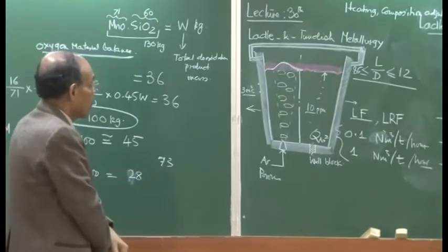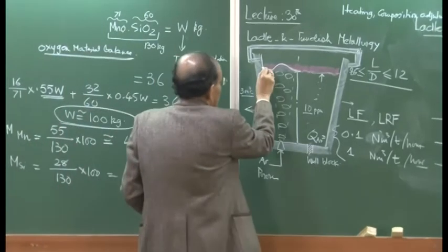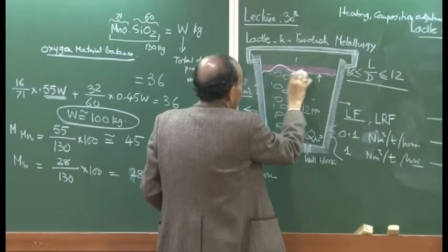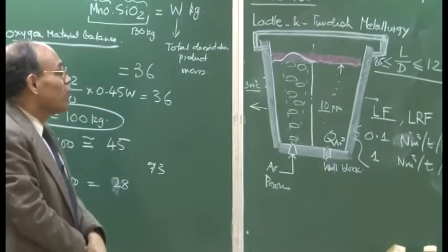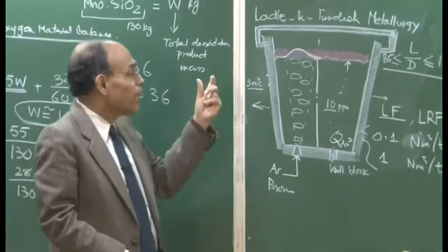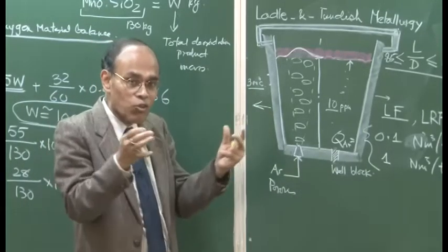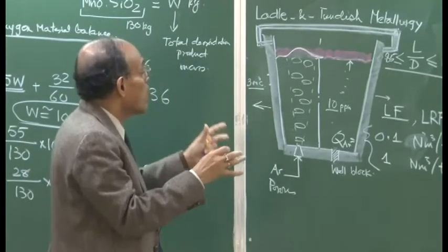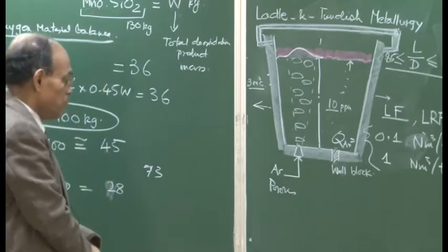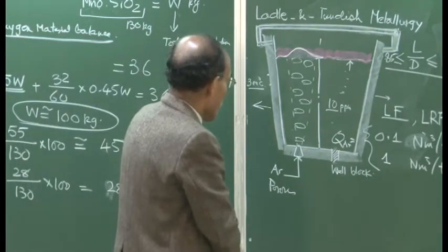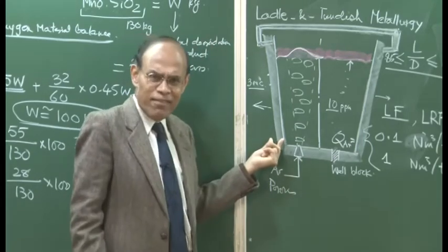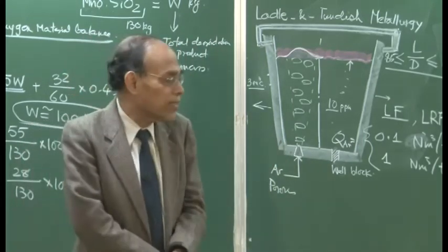impair the quality of steel, and this slag, the synthetic slag cover here as well as a top ladle cover, physical cover, will allow us to constrain the heat loss as well as reduce the extent of atmospheric reoxidation. The ladles are lined with refractories, it is to be expected, okay?